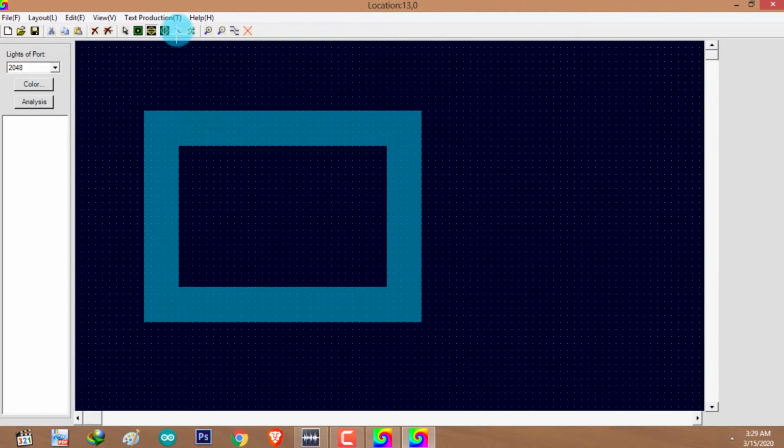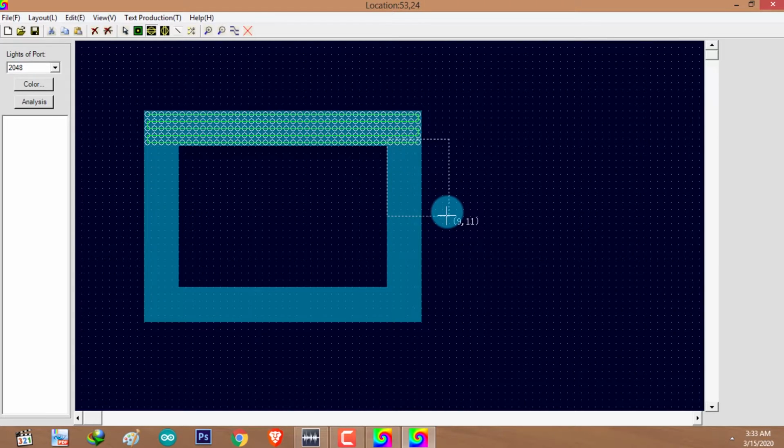Click one of these light vertical or light horizontal buttons. Click and hold your left mouse button at the start of the area to be traced. At the end of the section, I'm going to release my mouse button, which will place pixel reference points in the selection. Alright, I'm going to do it to the other sections. We have 2 vertical sections and 2 horizontal sections. If you don't want to make the selection, press the Escape button.